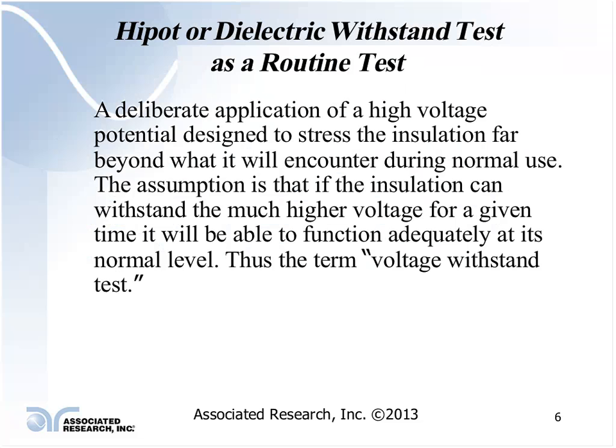And it's assumed that if the insulation can withstand this much higher potential for this given time period, it will be able to function adequately at its normal level throughout the life cycle of the product itself. And this is where the term voltage withstand test essentially comes from.